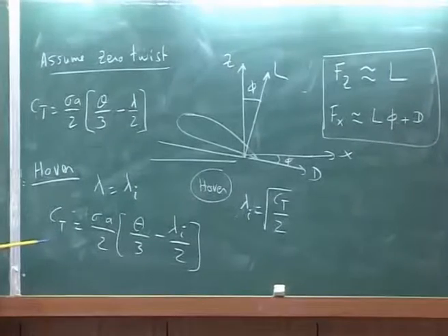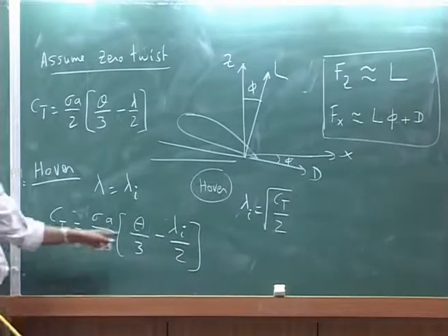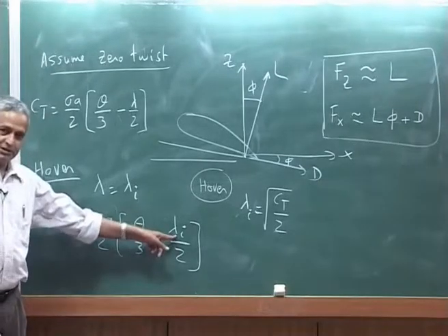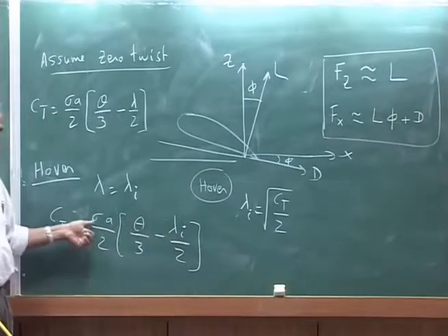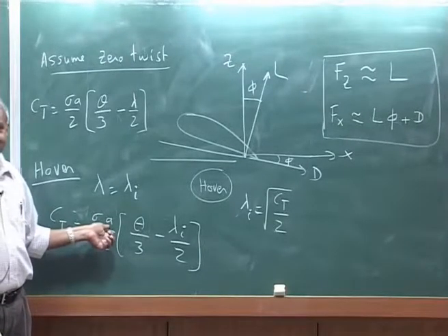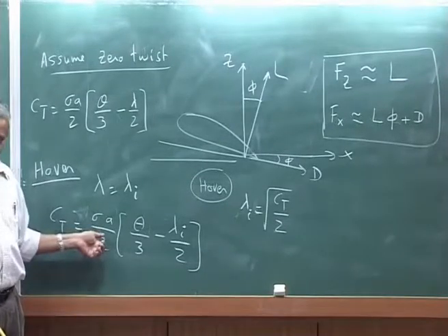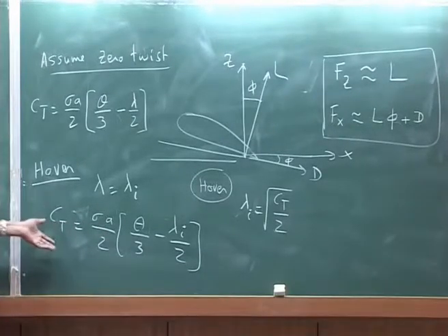Now, blade element theory is relating pitch angle, induced flow, solidity and airfoil characteristics, because all these are there. Number of blades, actually these are non-dimensional quantities. If you want, then operating condition is there, angle of attack, everything is there.